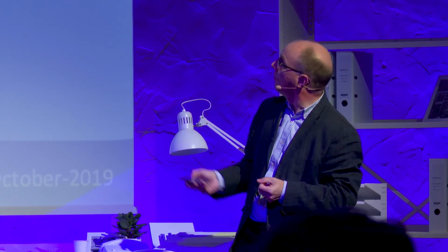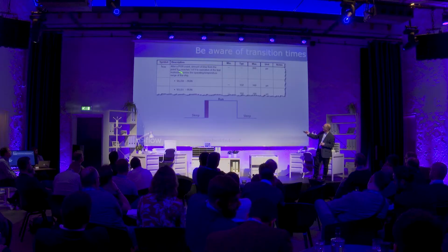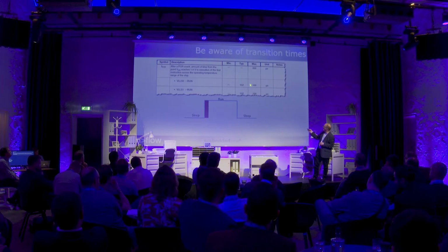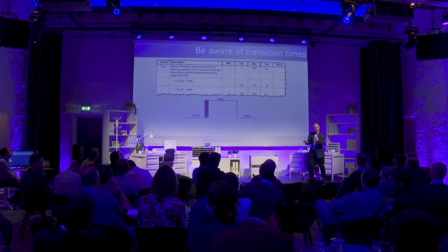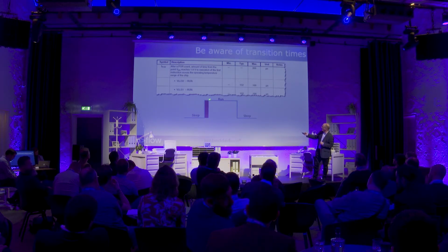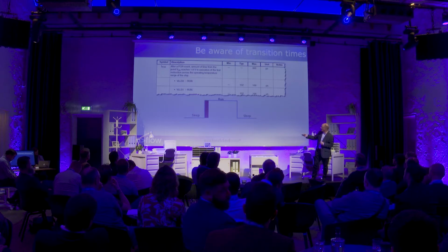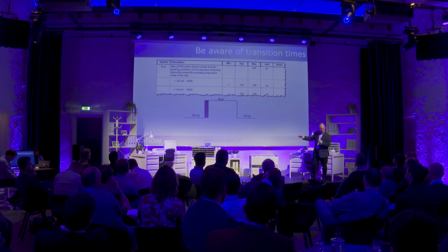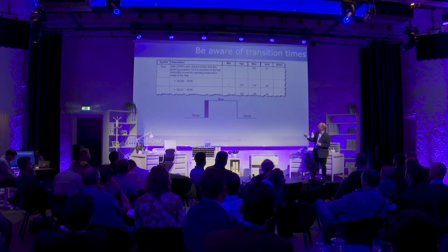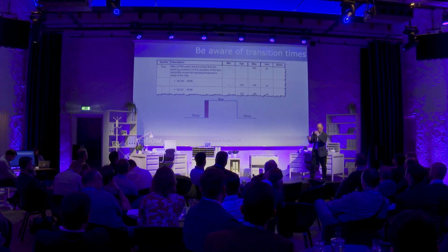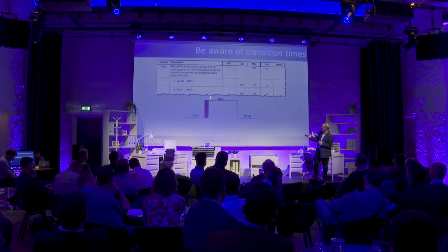And what does that mean? Well, here's a datasheet figure. To go from a particular low power mode into run, it can take nearly 200 microseconds. And of course, while you're doing that transition, the chip is likely to be taking the run current, not the sleep current, because all the logic's powered up, it's starting to want to access flash memory, the clocks are running, so it's in the high power mode. And if you're waking up on a very, very fast interval, this hidden phantom current can be quite significant in the design.